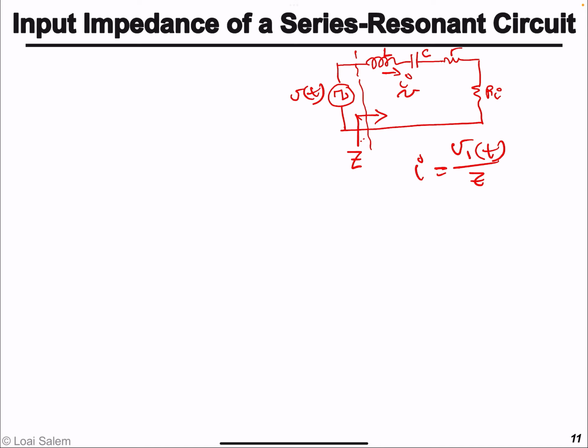We know that this RLC circuit essentially will only allow the fundamental component to flow, so the current is going to be, assuming the loaded quality is high, larger than 2.5, a pure sinusoid. So to find that fundamental current, we just need the fundamental component of the voltage divided by Z, and that's how we get I, the function of time. So first, we need to find the impedance Z of this RLC circuit.